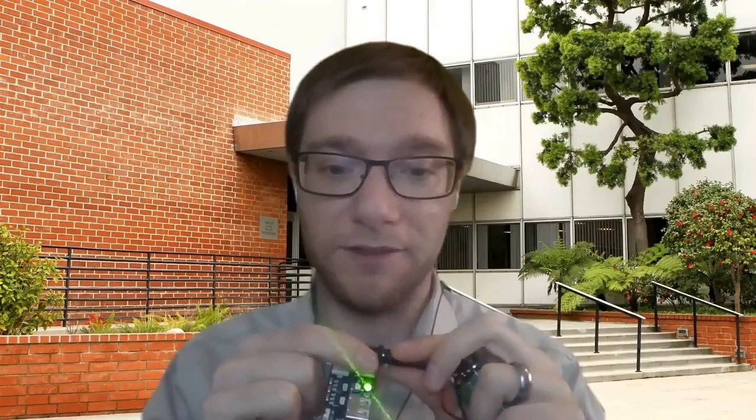We also are going to start with just using that breadboard to make some circuits and powering the breadboard with a battery. You did get a 9-volt square battery in your kit, as well as this little adapter. You just plug the adapter onto the top, and now you can plug the 9-volt battery into this power module. This thing should turn on and off when you press the white button. It basically goes onto your breadboard like that and allows you to build little circuits on your breadboard and then turn them on and off with the white button.